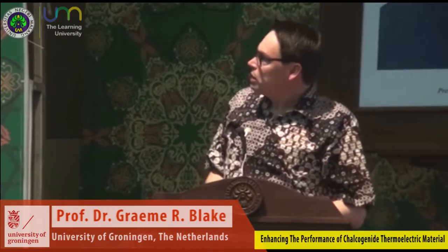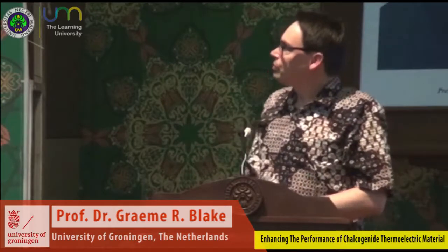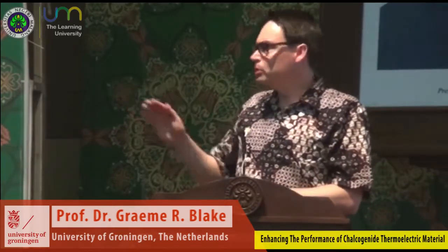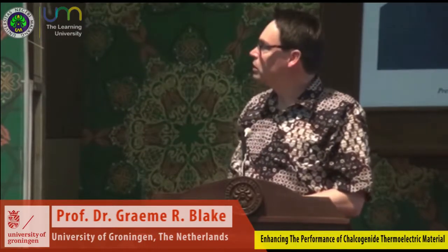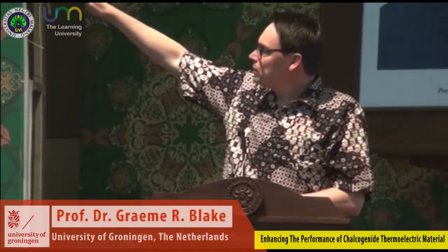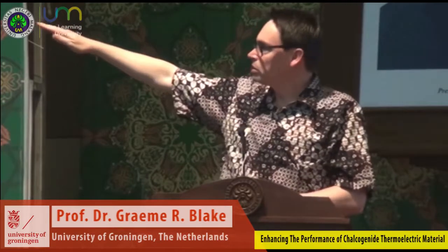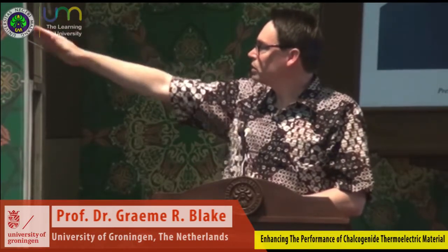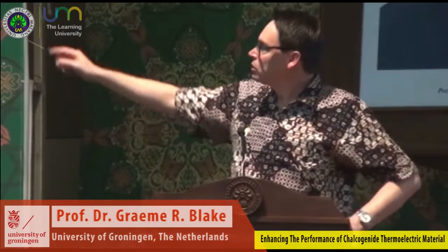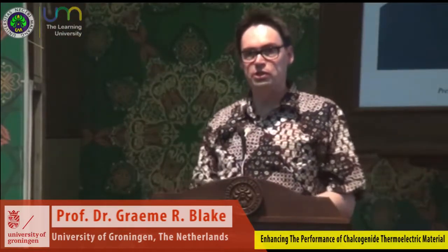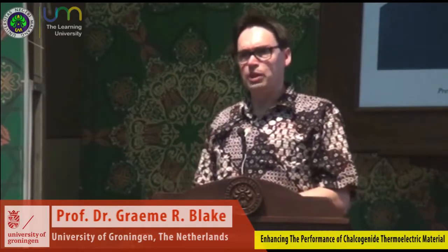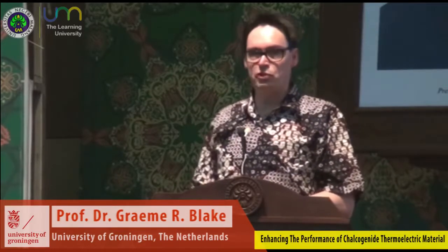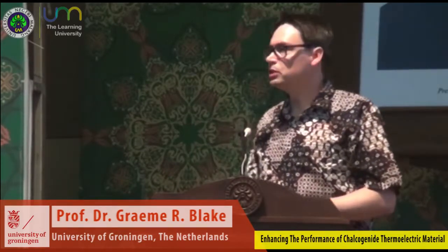So this plot here is a kind of plot of operating cost of a thermoelectric module for various general types of materials. So you can see from the plot that the operating costs are lowest on the right-hand side. That's for the highest ZTs. So those red symbols are for the chalcogenides. So those are mostly tellurides, sometimes selenides. So it's kind of unfortunate that we're stuck a bit with tellurides at the moment for the best performing materials. Next, please.